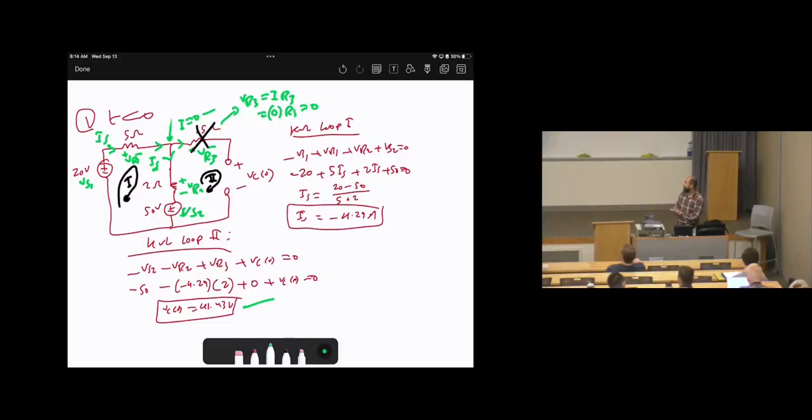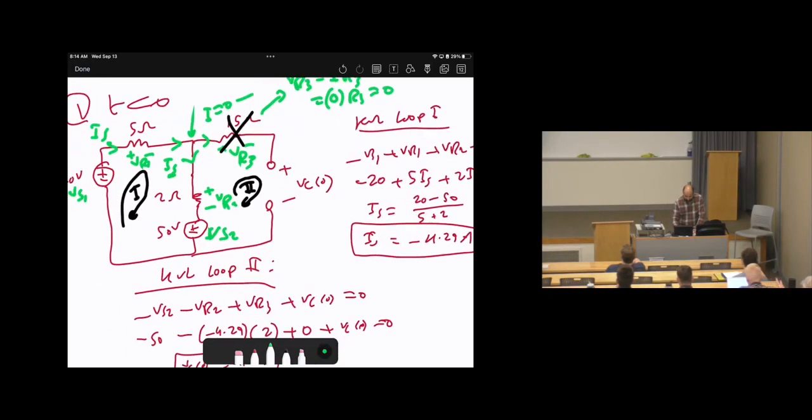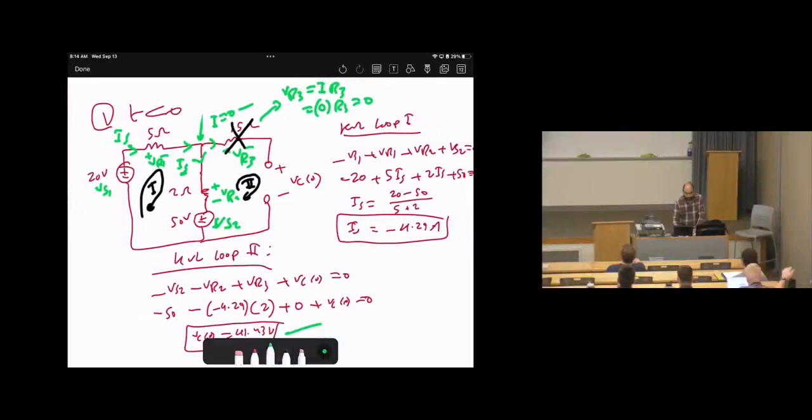So remember that the 15 ohms resistor, since there is no current flowing through it, or the current is 0, therefore the voltage I times R, which is 0 times R, will make it 0. Just like all this. Yes? How come there's a voltage across VC if there's no current flowing over there? How are we able to calculate a voltage across VC?